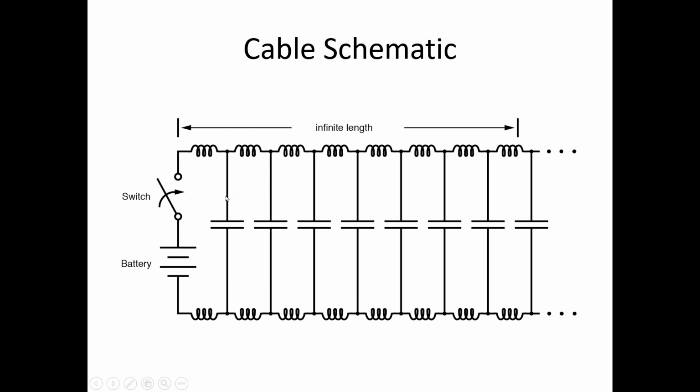And what I do want to point out is that there are actually no capacitors, and yet we're showing capacitance. And why is that? By definition, two wires separated by a dielectric material does not allow electricity to pass, but it may allow an electric charge to exist.